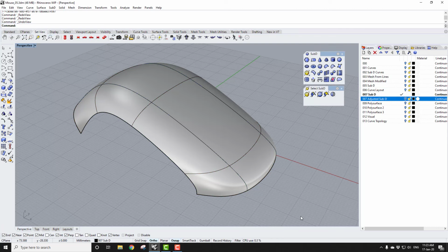At this stage, the sides of the shape are still open, and we have a number of ways of closing these off that takes full advantage of the fact that SubD surfaces are inherently smooth or curvature continuous. First of all, I can use the bridge command with an appropriate straightness and number of segments, and I can then use a command called stitch to close up the two remaining edge pairs. So let's take a quick look at this.